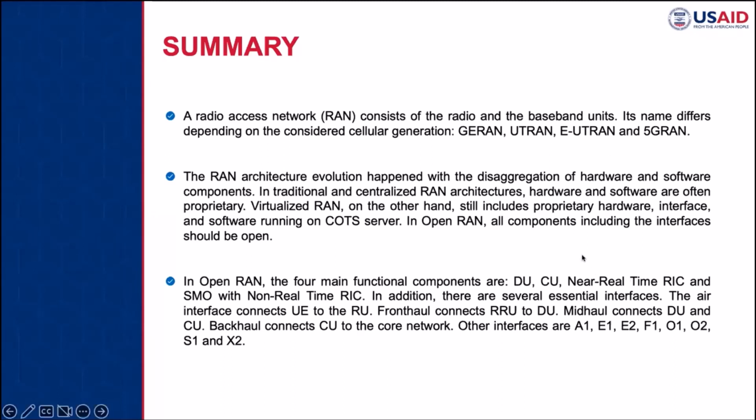Remember, the near real-time RIC is in charge of tasks that require less than 1 second of latency, like the xApps. And the non-real-time RIC is in charge of the tasks that support greater than 1 second of latency, like the rApps. Okay, there were also several interfaces that we have covered, like for example, the air interface, the front haul interface, mid haul interface, and back haul interfaces.